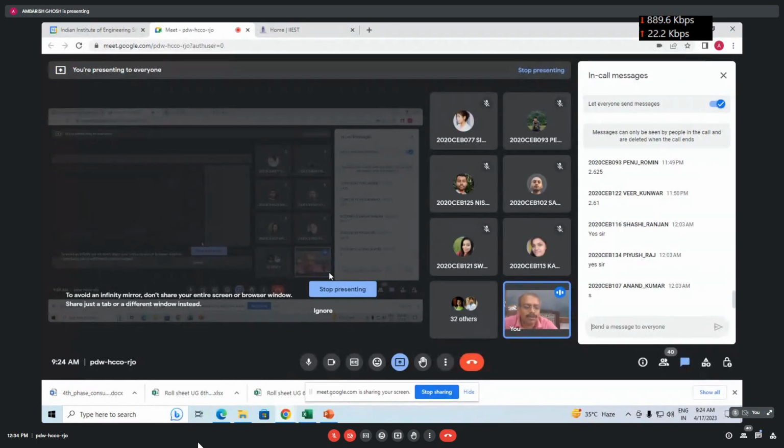Now link, you keep it in writing, don't forget it. Again, in the top 3D of the pile, you provide more links, and in the later part you can give minimum, because in case of earthquake there is possibility of hinge formation in the pile and pile cap. So this thing we can discuss even in next semester.